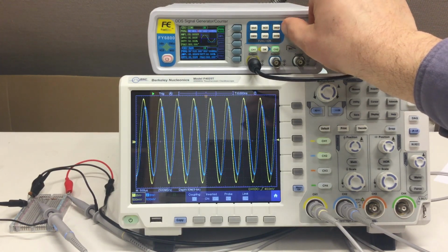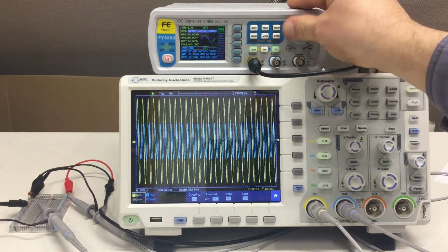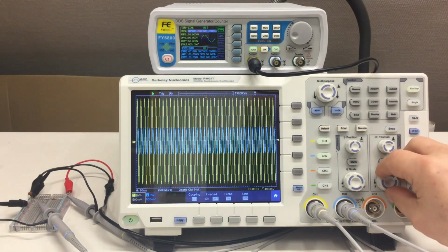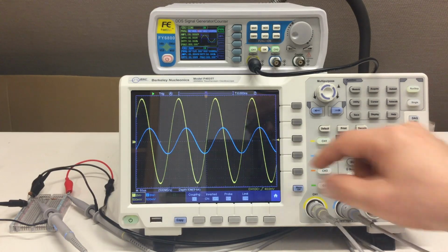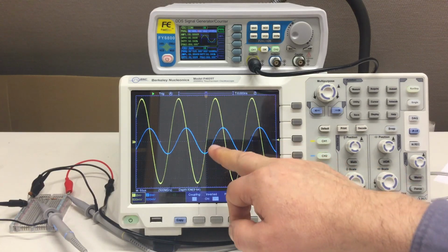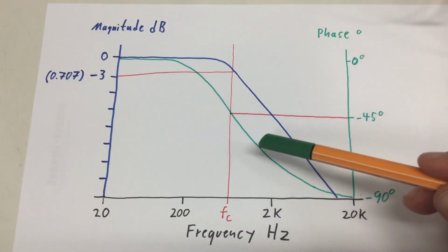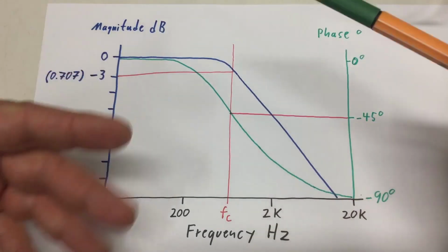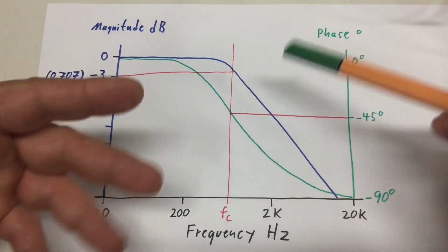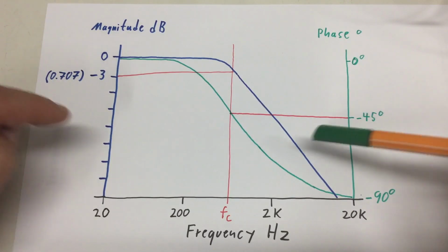Okay, and if I increase that, say, to 5 kilohertz or something, let me correct the scale. You see our output is now really low, and we have an almost 90-degree phase shift here. And that frequency response, in my case of an RC low pass, but of any device under test, you can visualize with a Bode plot.